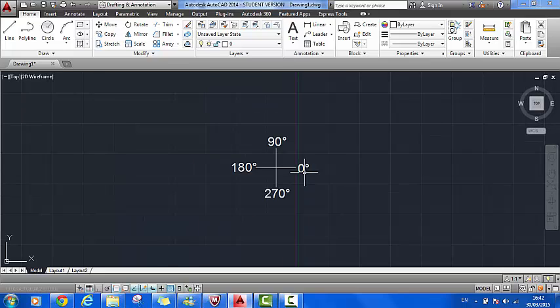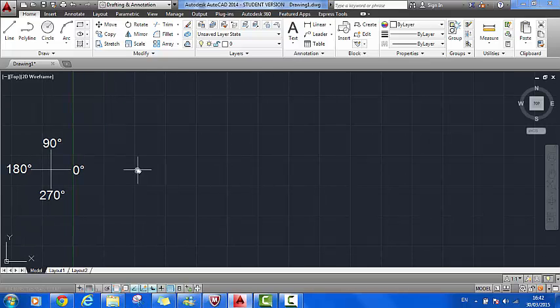So, back to creating my line. Alright, if I go up here to my draw ribbon and select line, it's going to ask me to specify the first point. Now I'm just going to click on the drawing space anywhere there. So that's my first point specified. Now I need to use my polar coordinates, i.e. a distance and an angle.